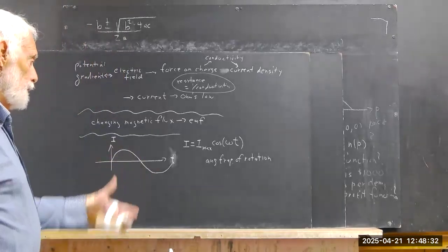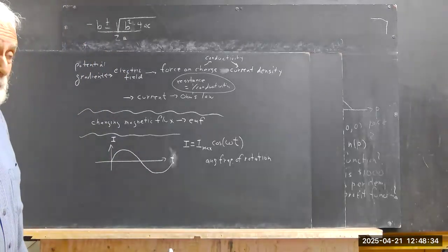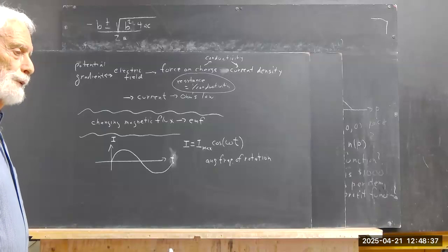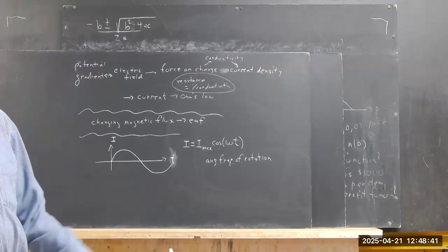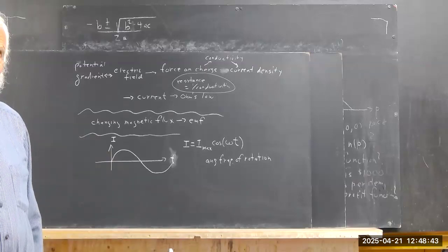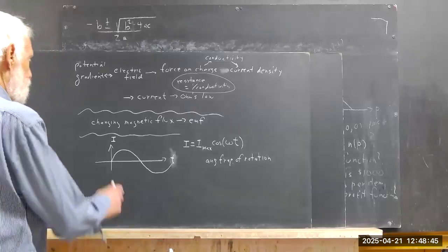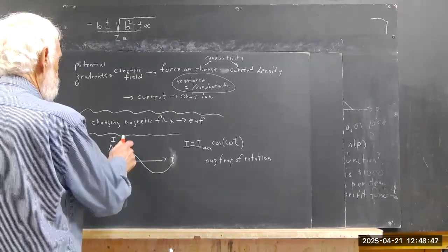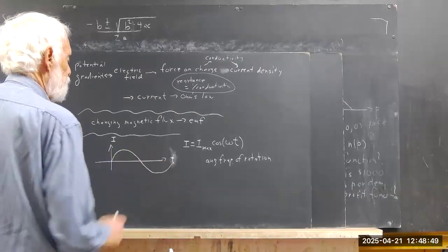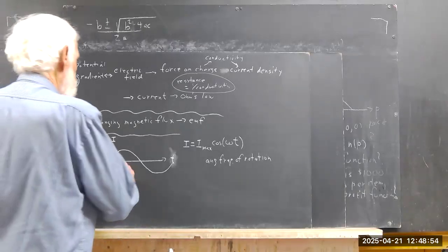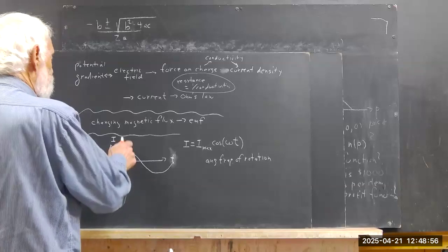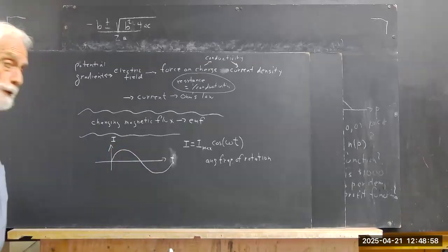Now, we do some funny little stuff between radians and degrees, because a lot of times we'll say this current is 90 degrees out of phase with that one. Okay. It's easy to think 90 degrees. We just think here it's 0, here it's 360 degrees, here's 90, here's 180, here's 270, right? Makes it easy to think, well, there's 2 pi radians, so there's pi over 2 and 3 pi over 2.